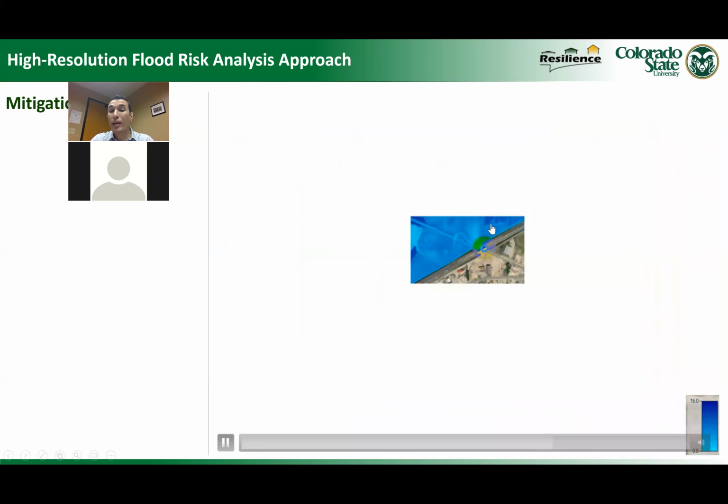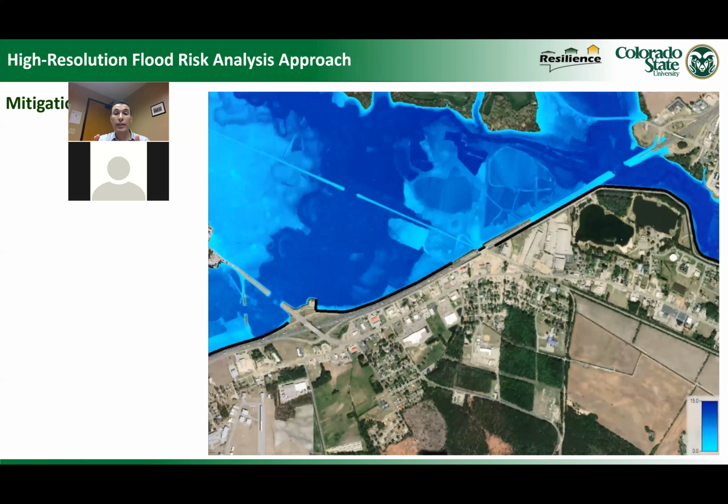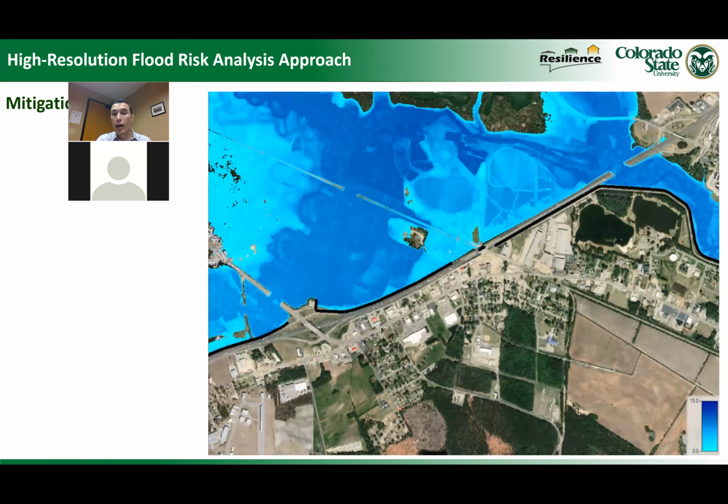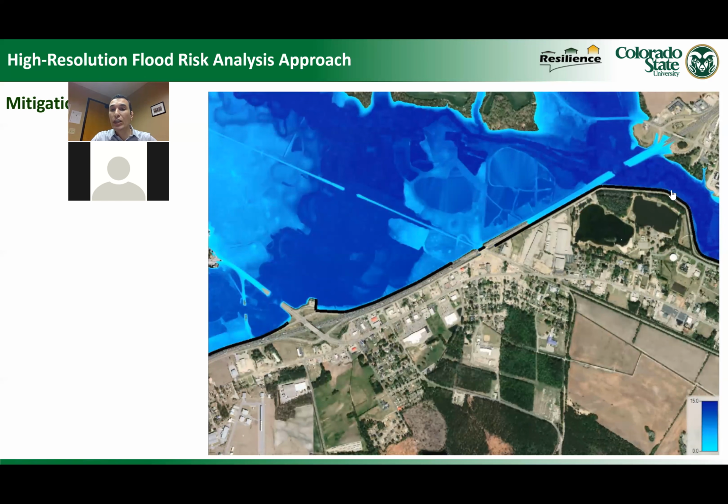It closed the water, but this simulation is one after many simulations, because when we did the floodgates alone, the water kept accumulating behind this gate, and the water made a reservoir action, and the water overtopped the embankment here and the levee system here. So we needed to enhance the levee system. And when we enhanced the levee system, the water breached from the embankment of the highway. So we needed to enhance the highway. So this is one of our mitigation scenarios to control the hazard itself.